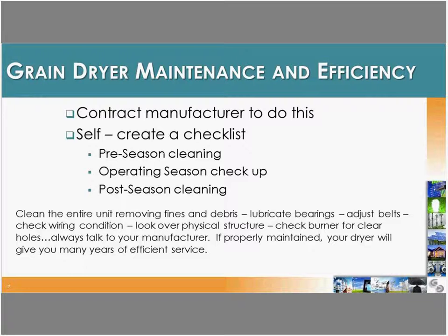A question here. Sure. All right, we've got, what is the highest moisture content that the first type of dryer, the natural air low temperature, can efficiently handle? You want to keep that down to 24% or less, I would believe.